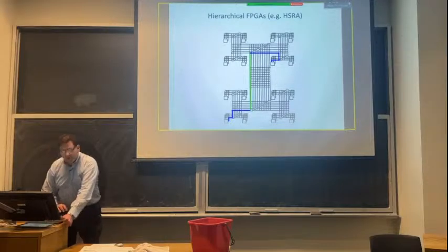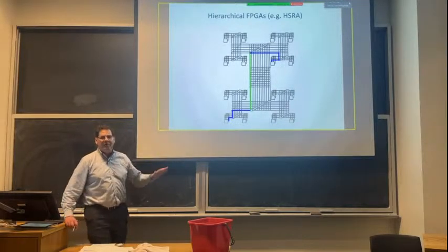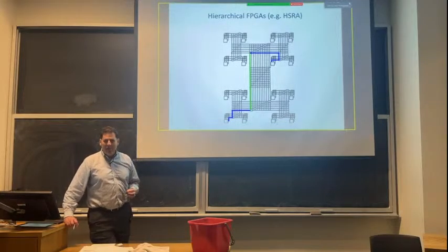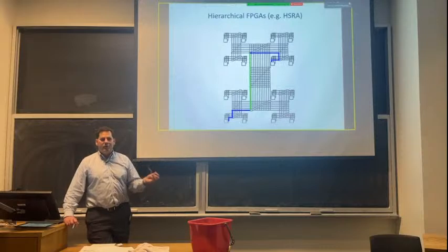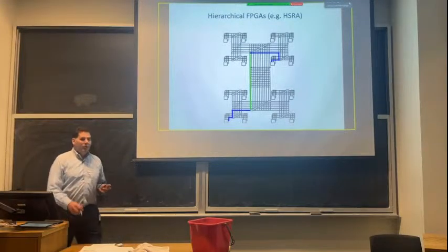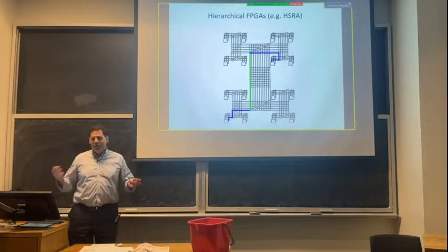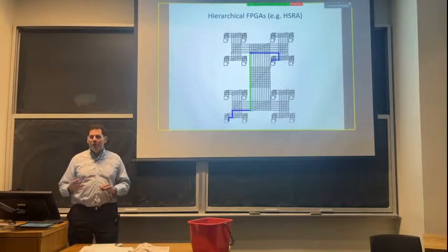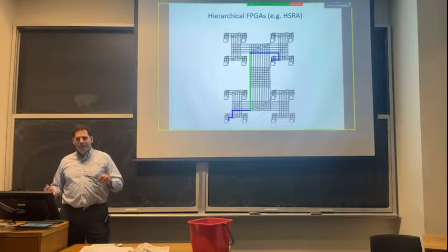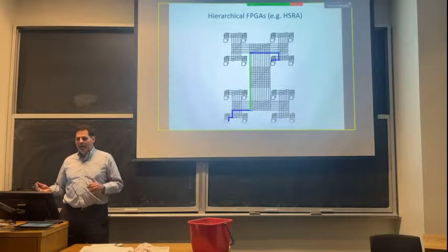Okay, so we talked about just kind of big picture FPGA architectures. So we saw there are a few different logic elements. None of them scale to really big sizes, so we have to connect them together with some kind of routing network. And the first kind of routing network we looked at were hierarchical ones. And hierarchical ones are inspired by the fact that circuits are hierarchical, so you don't need as many wires essentially at higher levels of the hierarchy as the sum of all the wires at the lower level of the hierarchy, which helps you scale your design.